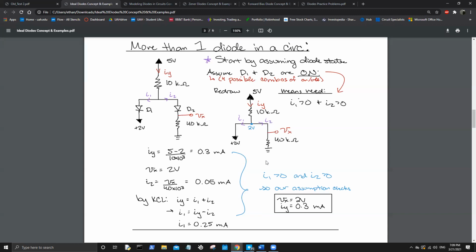Therefore that changes the answer, because then you'd have 2.7 volts across that I1 branch. So the voltage drop across the resistor isn't 3 volts. It'd be 2.3 or something, which then you'd have to subtract the 0.7. So it would change the 1.4 answer. I doubt we'd have to assume that, but if so, all that would end up doing is changing your IY, your supply current.